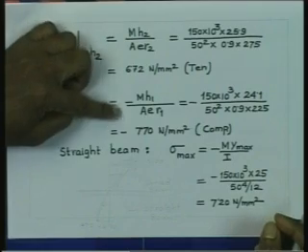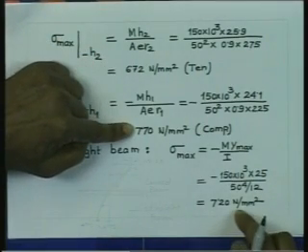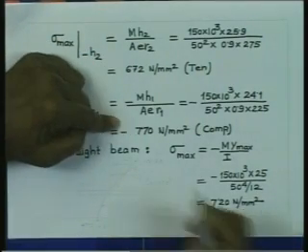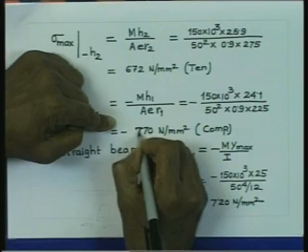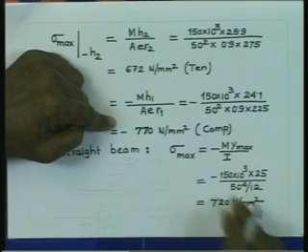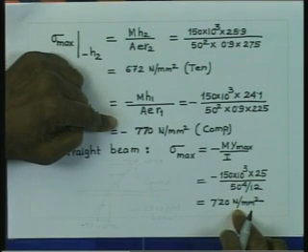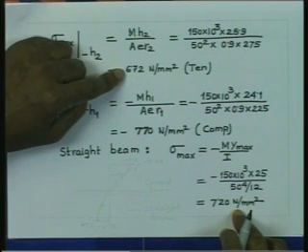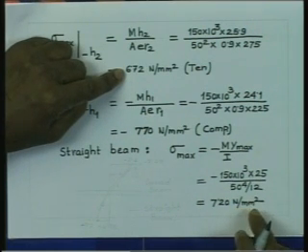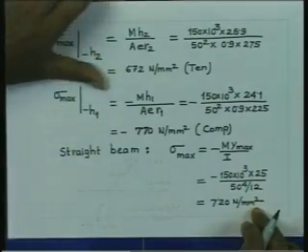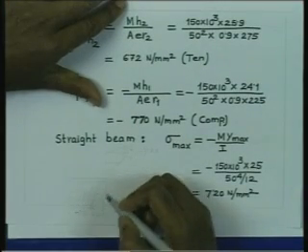So, you can see that the maximum stress that we are calculating is underestimated. This value is 7.7, whereas the straight beam formula gives us 7.2. Similarly, the minimum stress is going to be overestimated if we make use of the straight beam formula. Just to compare the two variations, we can plot it.